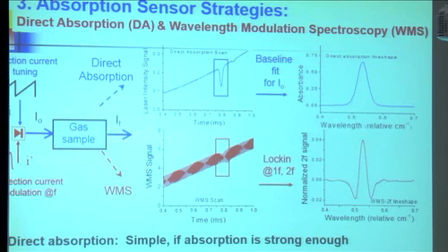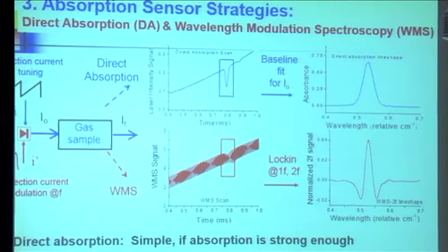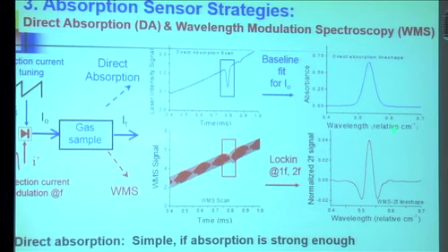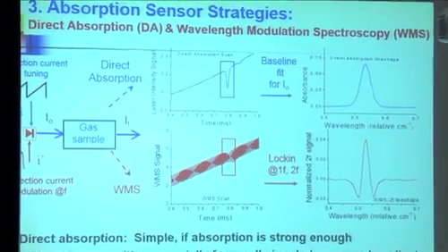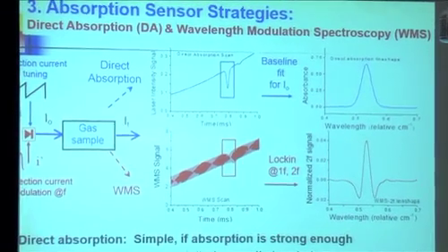And I like to say it's also 10 to 20 times more complicated, because we're dealing with some electronics and you have to be careful. But it turns out this method has some advantages that I hadn't fully appreciated. Because you're sampling this signal at 2F, and I'll tell you in a minute why we do 1F, you're only looking at the signal content near this F. It means you're not looking at low frequencies. Any low frequency noise is kicked out. It has big advantages for noise rejection.